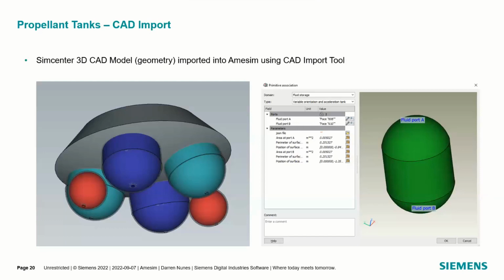So we have CAD import for tanks, where you can slice it and look at different wet surfaces through the different dynamics of acceleration and external forces. And then you can get different bend areas or radiuses. You can have a better understanding of those pressure drops or flow coefficients based on the actual geometry from the CAD.